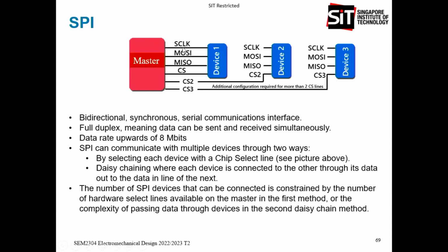The other type of device that we have is the SPI. SPI is a serial interface, but it provides full duplex operation. I2C, can it provide full duplex? What is full duplex? Both can talk and listen at the same time, right? What about I2C? Cannot, right? Because we only have one data line. On that data line, only one device can talk, or the rest are all listening. So it's half duplex for I2C.